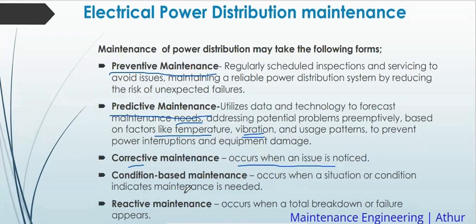When there is a condition, for instance, when I was explaining about the transformer, I showed you that it outputs three-phase, four-wire. Now the fourth wire is a neutral. That means that if there is what we call unbalanced load or no load balancing, when you are supplying a customer, you supply him with one phase and a neutral. You find some customers are connected on red neutral, others are on yellow neutral. So at some point you will find that one of the phases is overloaded.